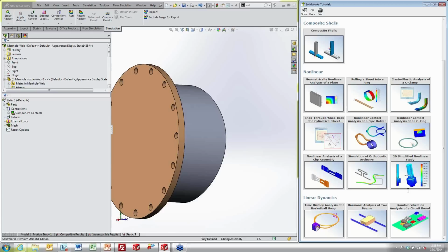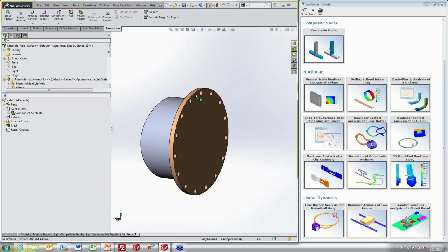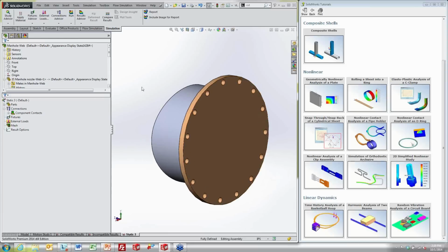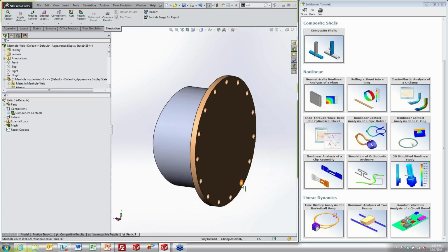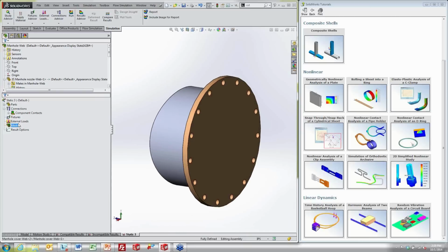I have another question from Igor. Is there any way to open up a single surfaces model straight from a scanner? So you can scan data directly into SOLIDWORKS. You'll probably have some sort of STL file. The types of files that SOLIDWORKS can open are the STL or the step files, the IGES. You can open those. It'll be a bunch of surfaces. And SOLIDWORKS simulation can run analysis on surfaces. But what you'll be using instead of the solid triangles that we saw here are shell elements. So those are completely flat triangles. So you can do it with surfaces if you wanted to.